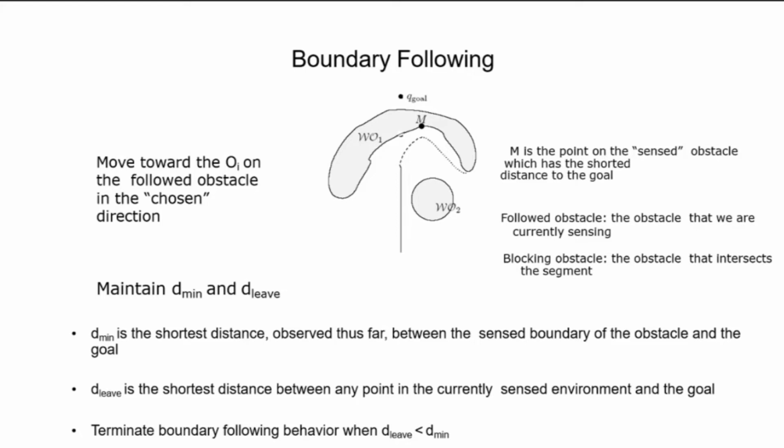So this is an example also where the robot was moving towards the obstacle. It finds the point M, goes towards M, but then after M, again this is concave. Okay, and this happens very often for concave obstacles. Now there is no other way, so it has to use the bug algorithm, or the tangent bug, follow the profile, and then go like this, and then come to the goal.